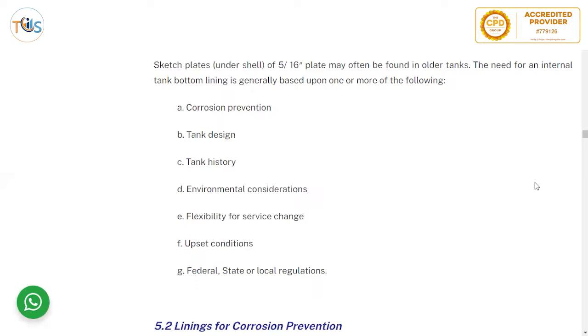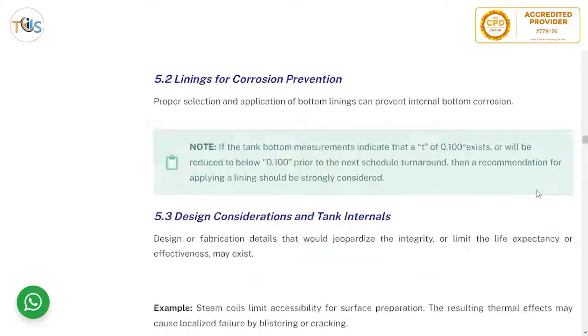The need for an internal tank bottom lining is generally based upon one or more of the following: corrosion prevention, tank design, tank history, environmental consideration, flexibility for service change, upset conditions, federal, state, or local regulations.